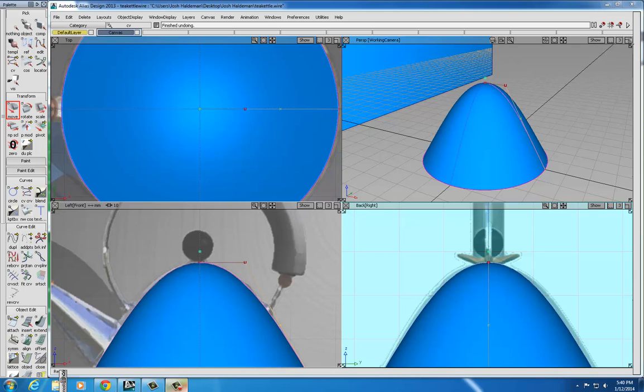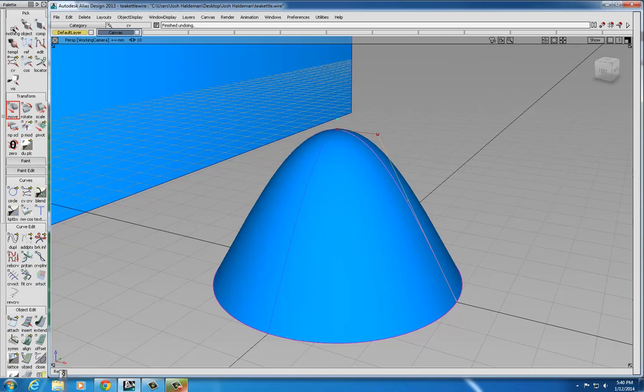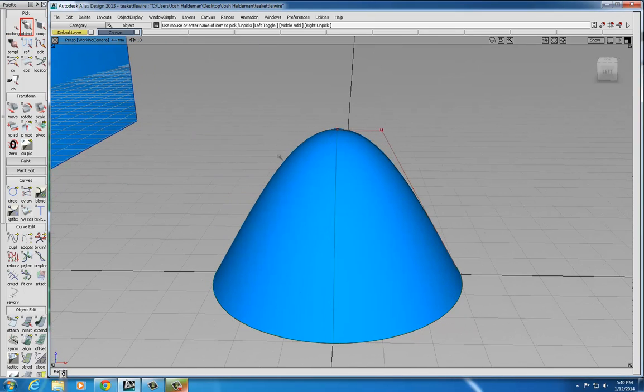So I'm going to go into my perspective window to do this operation. I'm going to choose pick nothing, pick object. This will ensure that I've got everything that I want deselected here. And then I'm going to just pick all the parts that I've created so far for my tea kettle. So that's the body, the base, and the curve that I used to create the body.